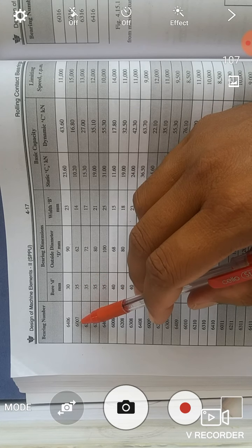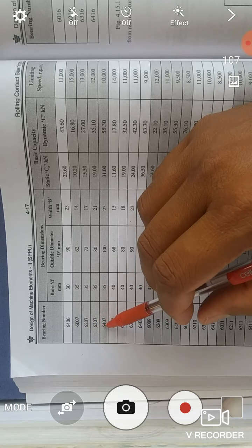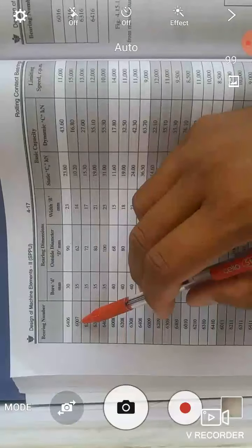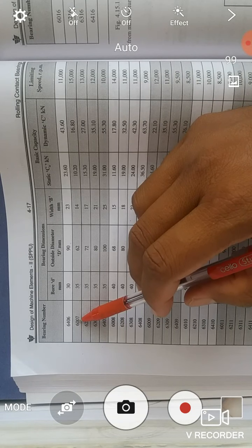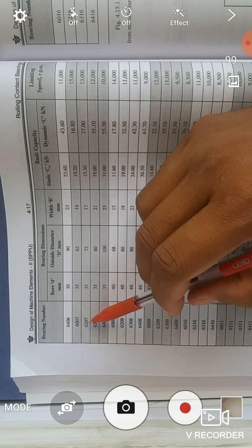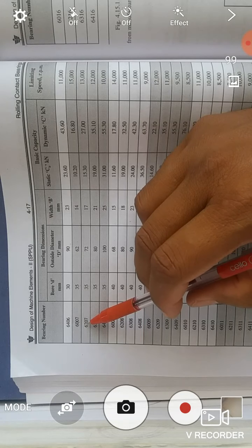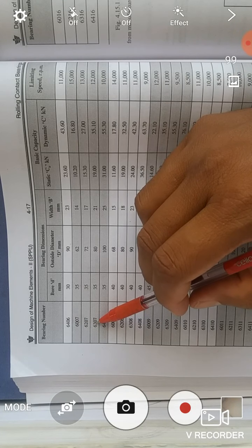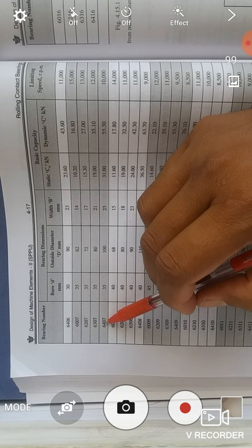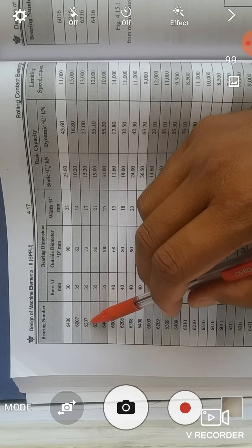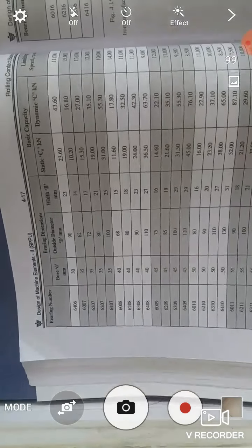If we focus on the second number, so 60, 62, 63 and 64. So the second number is related to series. And what is the series? Series is nothing but the load bearing capacity of the bearing. If 0 is there, then this is extra light series, that is load carrying capacity is very less. If 2 is there, then light series, the capacity is more than this extra light. Then 63, this 3 is medium, and 4 is heavy series. So 64 type of bearing has the maximum load carrying capacity as compared to 3. So 0, 2, 3 and 4 become the four types of series available.